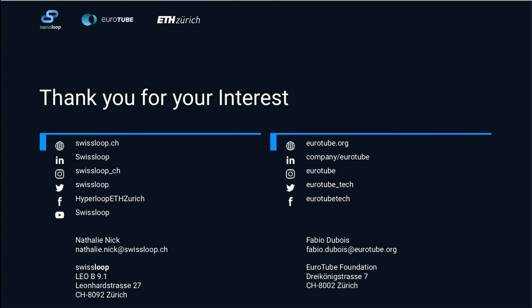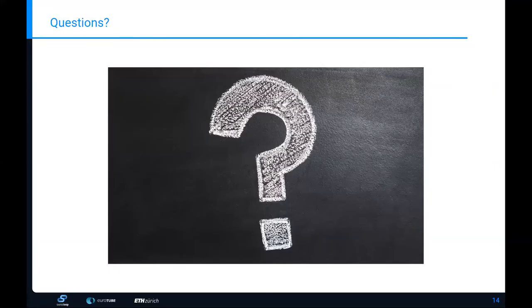So every pre-stressing element has 195 kilonewton. So it's 70% of the characteristic ultimate load. This is typical according to Swiss codes. And you do not connect the pre-stressing elements between 2 sections. You just pre-stress one section of 20 meters, you fix it, and then you decouple it. So you have the next section, which is also an individual pre-stressed structure. The only connection is actually this joint, the red one, which I showed you.